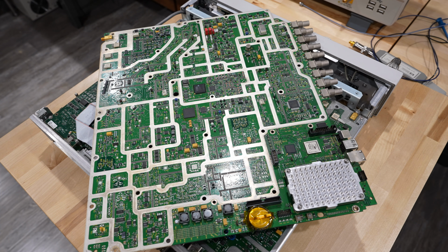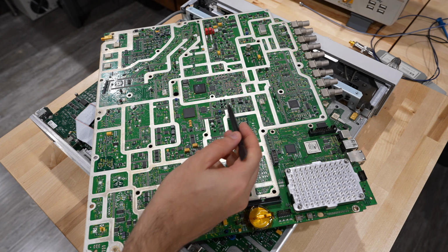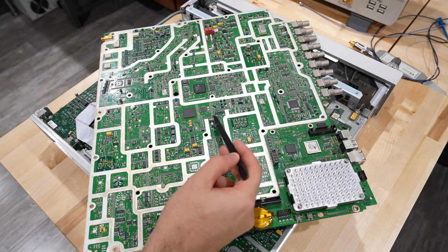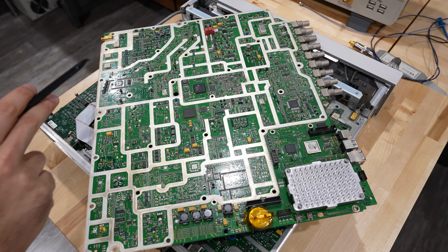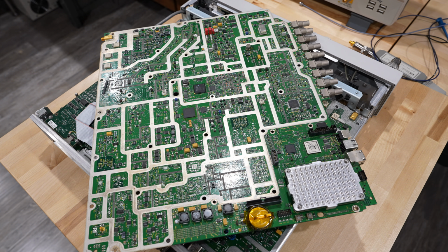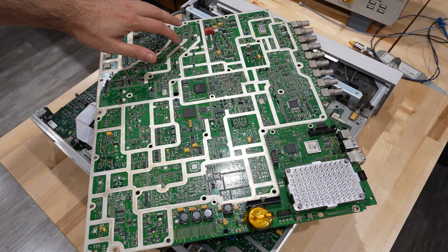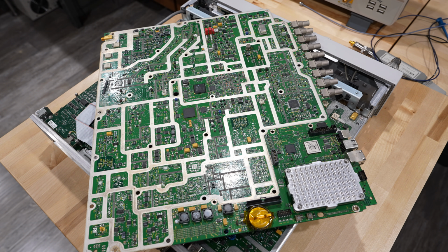So I have this donor board that I've been using and stealing components from over the years for various repairs. This is not from the same instrument model at all, but as is often the case, Keysight and other companies reuse a lot of the architectures and components across different models because it's obviously more convenient and the architectures aren't always changing drastically. If you look carefully in the middle, you can recognize a very similar structure between the Fractional-N divider, FPGA, and the phase detector. So we're going to steal this phase detector and put it on the other board and see if it makes any difference at all. And there's a lot of other components in here if you ever need to steal some. In fact, I've taken some amplifiers from here and a couple of other things over the years.